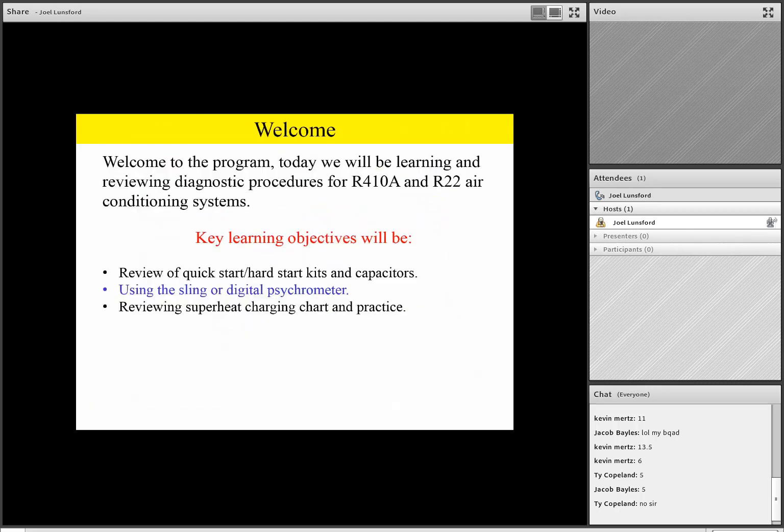Okay, so again, welcome to the program today, and we will be learning and reviewing some diagnostic procedures specific for 410A and R22 air conditioning systems. Some of our key learning objectives today will be review of the quick start kit, also called a hard start kit, using the sling or digital psychrometer to find wet bulb, dry bulb, and relative humidity of the return air going into the unit, and reviewing superheat charging chart and some practice of that superheat charging chart. Now please remember, team, whenever we have a piston on the indoor coil, we'll need to utilize the superheat charging chart.